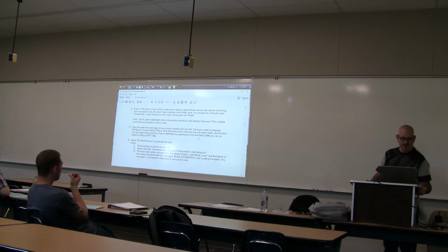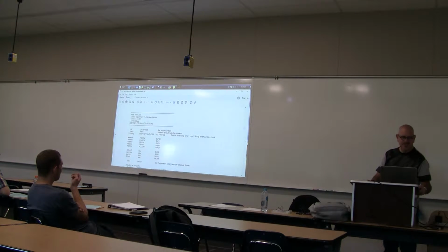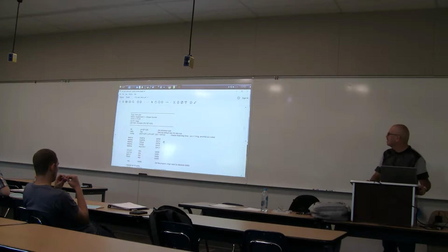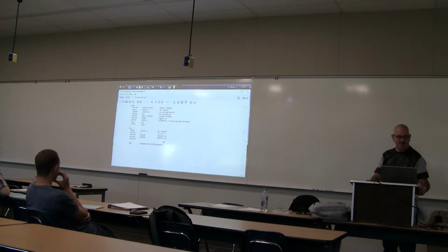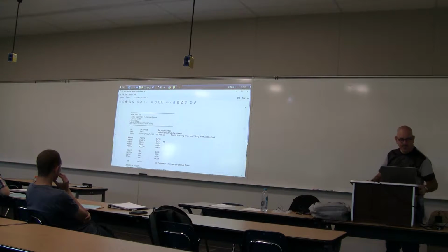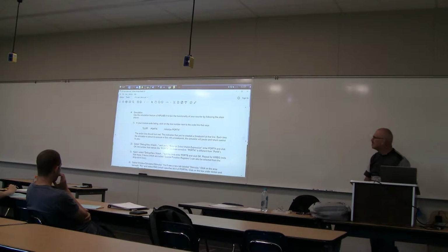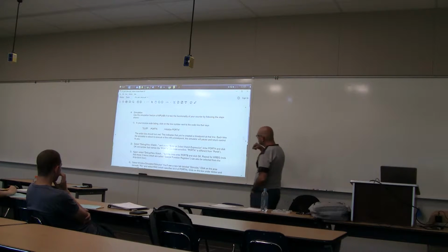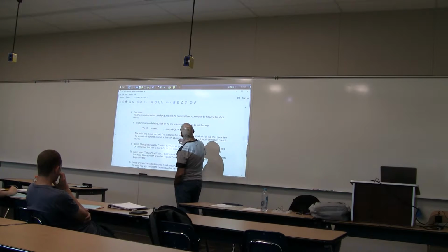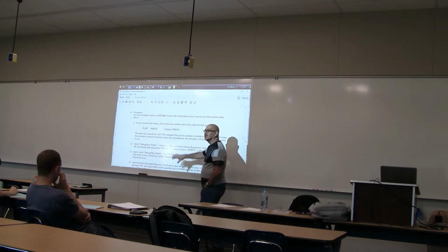So you'll go through a wizard and you will put this following code into an editor window in MPLAB X, and it's about a page worth of code. And then you'll go ahead and assemble this, and you'll use the simulator inside the tool to test this code and see what it does.